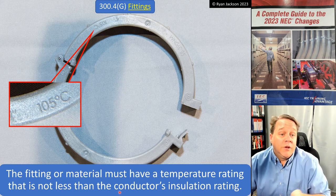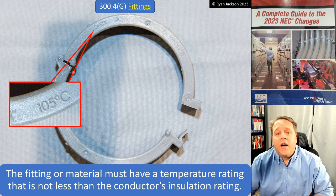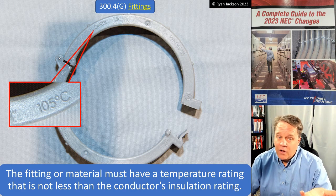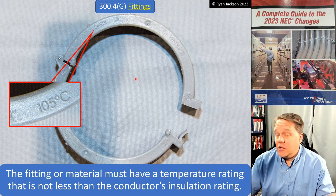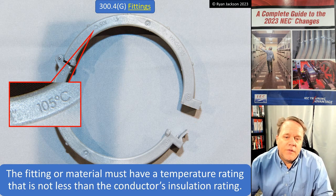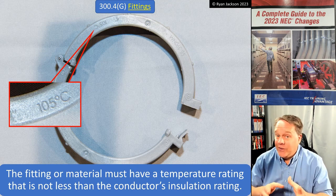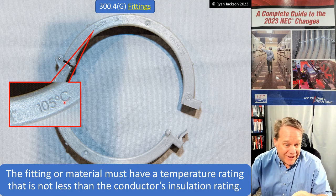This rule probably ought to say that the fitting must have a temperature rating not less than the operating temperature of the conductor. What if I'm installing 90 degree C rated conductors, but I'm terminating them at the 75 degree column? Well, probably ought to be able to use a 75 degree rated fitting. So maybe some work to be had on this section, but I think we both know the real reason that I'm showing this photograph. It's not necessarily because of temperature rating.